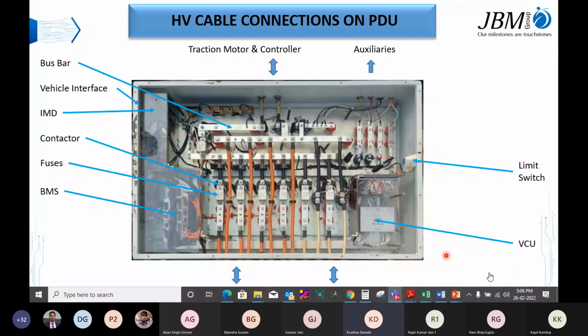And the same thing with the cable. Lange suggests using a 70 square mm cable, whereas we are using 95 square mm. If you reduce it to 70 square mm, that is also a cost saving. Yes, that will definitely be a cost saving, but it needs to be properly design reviewed.